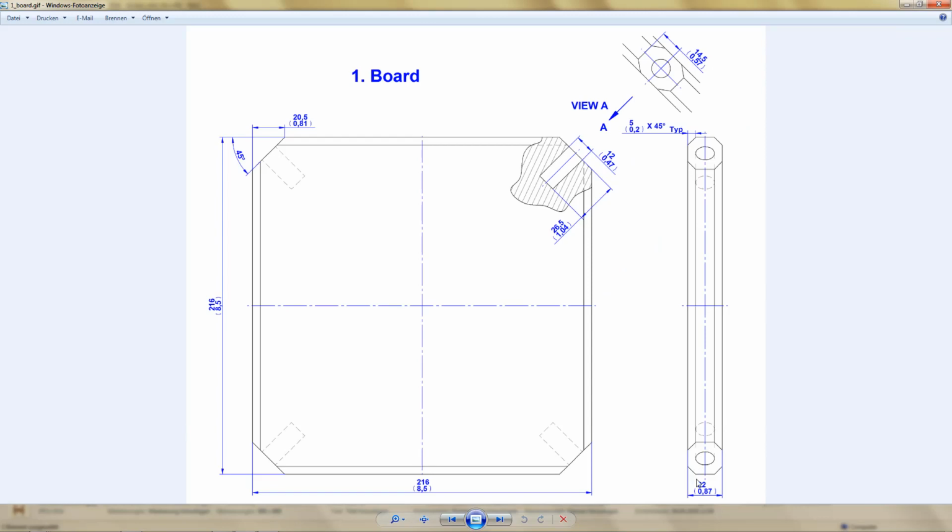Over here you can see that this board has a height of 22 millimeters, and we also have beveled edges here which are 5 millimeters, and we have these cut corners here. And on these corners we have holes, and this is where the pins go in. And these holes have a diameter of 12 millimeters and they are 26.5 millimeters deep.